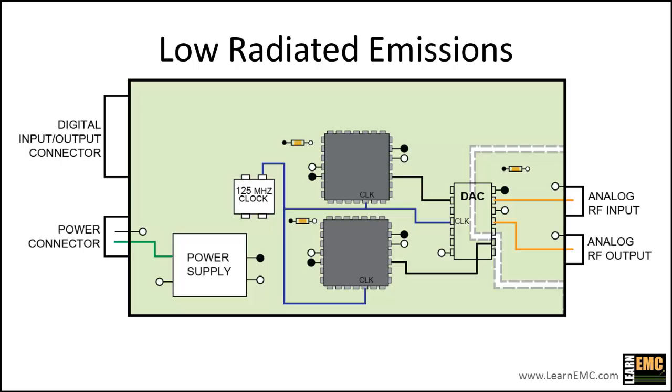The original design for this board has a gap in the ground plane that separates the area under the analog section of the board from the rest of the ground plane. The only connection between these two ground planes is the connection made internal to the DAC.